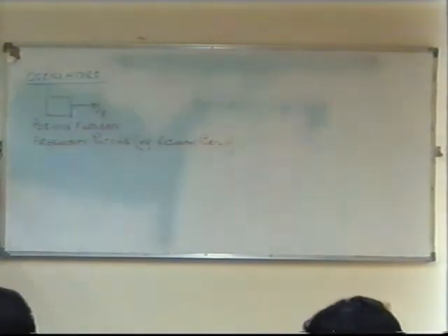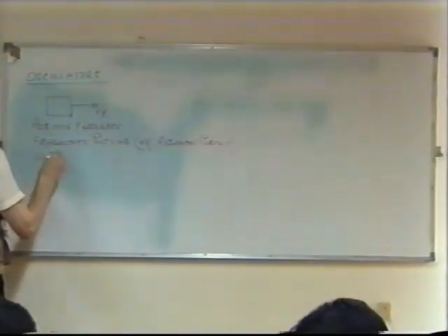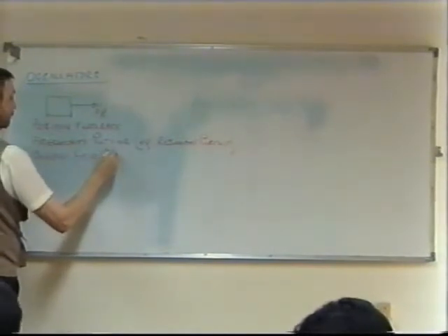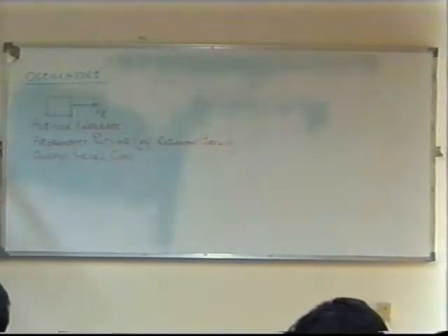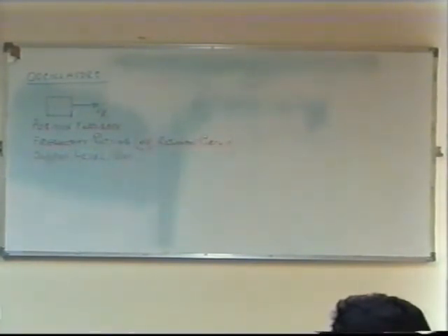There must also be some control on the output. Output level control. Three basic conditions. The reason for this output level control is that with positive feedback, if you remember the formulas that we used, you only need a very small amount of positive feedback to get an oscillator to work.